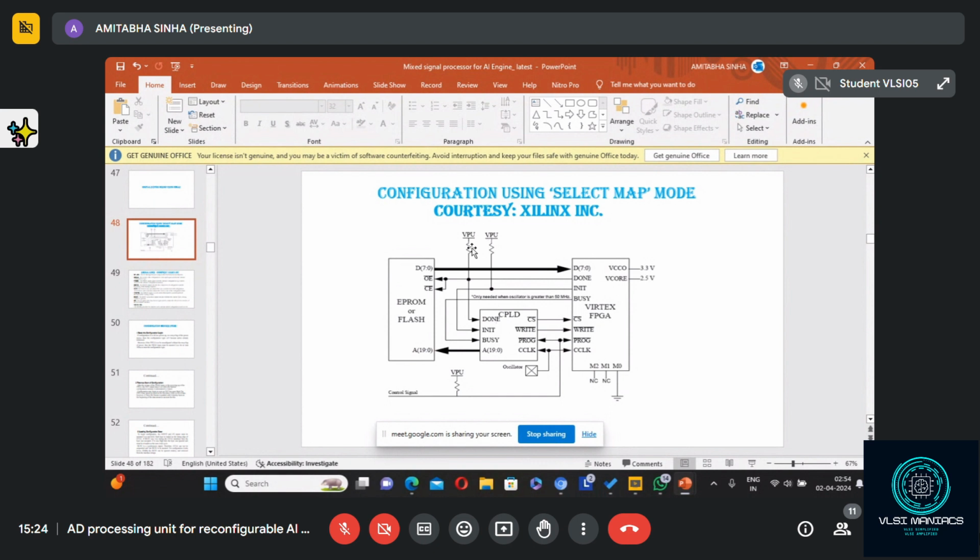The starting address must be there, because for bit streams, there are different sets of bit streams, maybe for FIR, IIR, etc. How to identify that? So the starting address of the bit streams and how many bytes are to be transferred. This starting address will be stored in a register within the CPLD, and that will be given by the CPU.